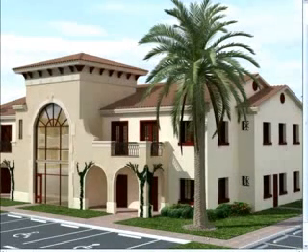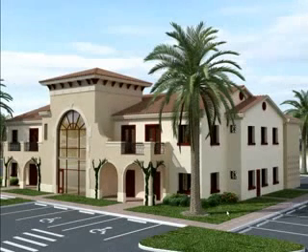And another important consideration when using displacement, at least for something like grass, since it does increase render times, make sure you use it only where you need it. In other words, for areas in the background of a scene, like the small area of grass back behind the building here, there's no point using displacement when the object is too far away from the camera for the viewer to tell. I cropped this particular image when I created it, but if I allowed more of the grass in the background to show, it would be really quite obvious that no one could tell if this grass was mapped or if it was displaced, like the grass that you see here in the foreground.